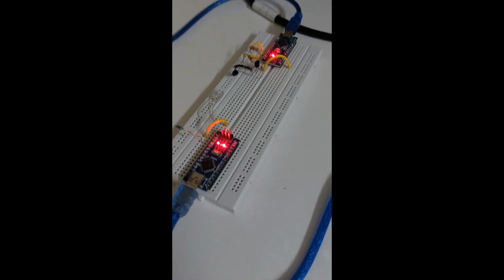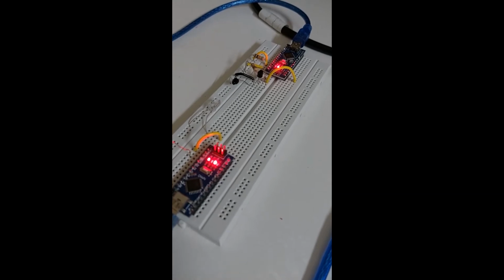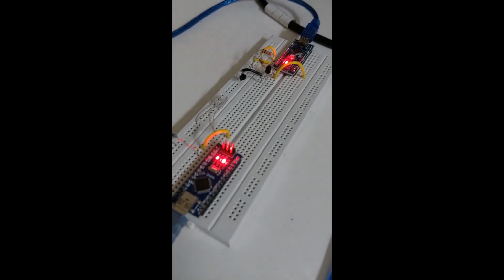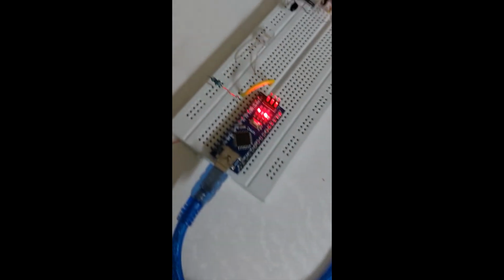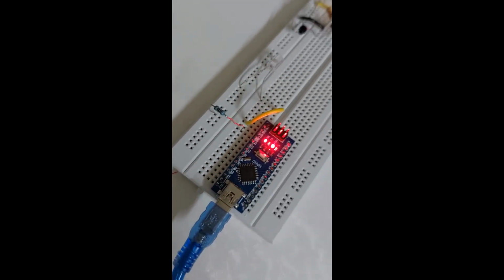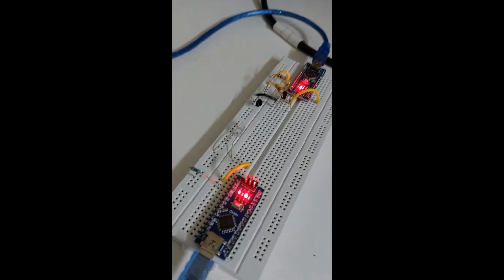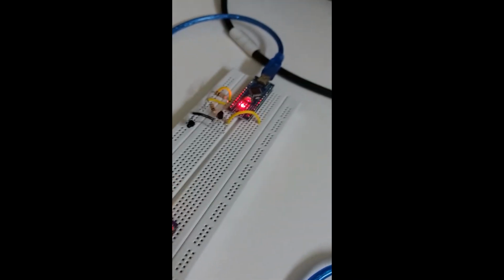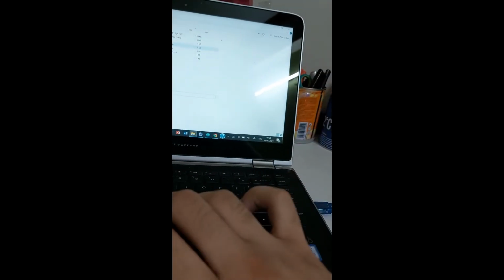The Arduino Nano and Uno and other boards also have the capability of using UART for serial communication, and over here we have used that. We have connected the transmission and receiving pins of these Arduinos to infrared LEDs and a circuit using a photodiode, and we will use these along with Python using the library PySerial to send data between these two computers.